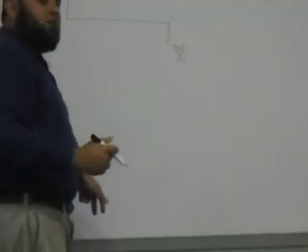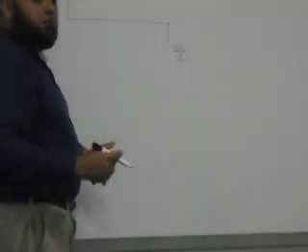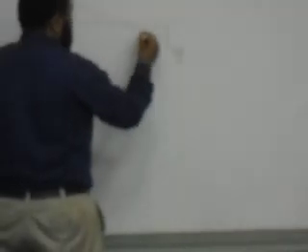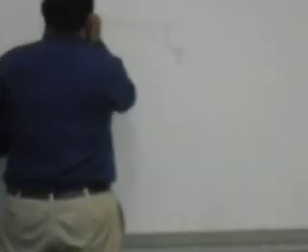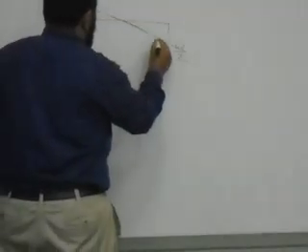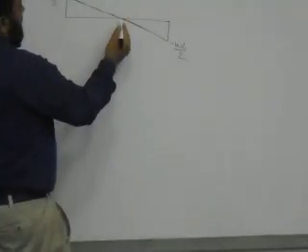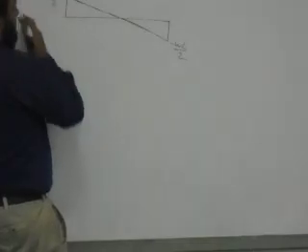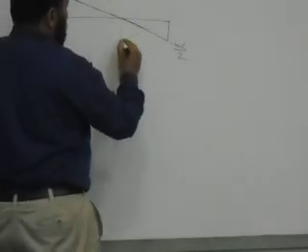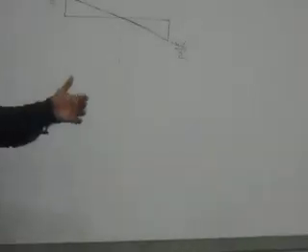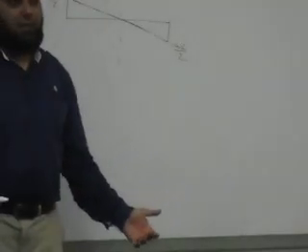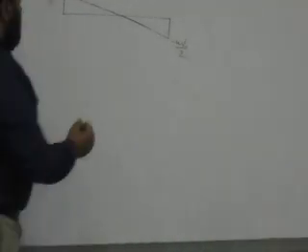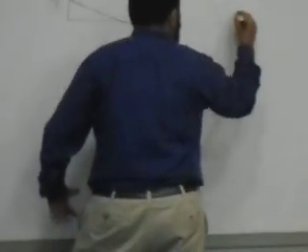And the bending moment will be what? One order higher than the shear force, which is a parabola. Okay? So in this case, my straight line is not perfect yet. Where's this thing from symmetry? WL over 2, negative WL over 2. So this is exactly at the middle. There's zero shear exactly at the middle, so this is my shear force diagram.